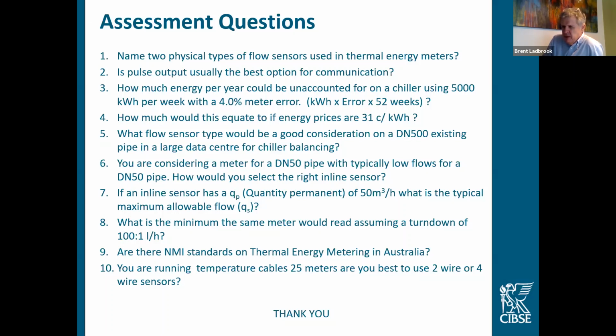I believe it's also possible with an inline ultrasonic meter, although I've never actually had to do it here in Australia because I've never seen glycol being used. Maybe it is somewhere. And I'm not sure about mag flows, but it is important because that energy or the K factor would vary from fluid to fluid.